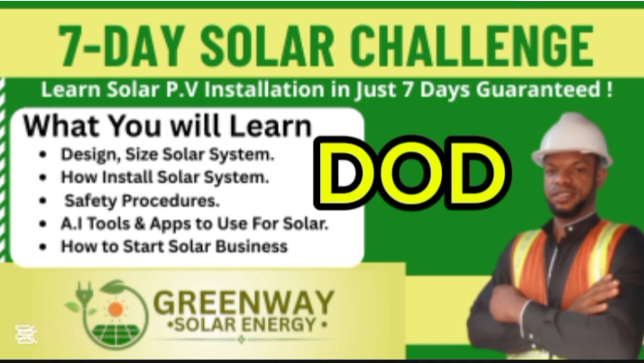And this is one of the reasons why you hear people complain about their solar installation. It now looks as if the solar installer doesn't know what he is doing. You understand? If they continue to exceed the depth of discharge over time, within 3 months, the system will begin to have problems.